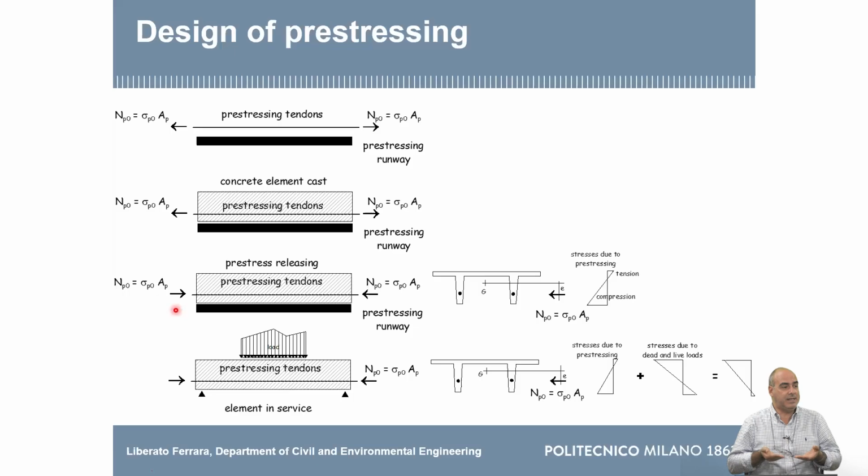It tends to detach from the continuous contact on the bottom and tends to support itself on the edges. But as soon as you do this, the element immediately starts being subjected to its self-weight because you have detached it. So there is never in design a condition where you have only pre-stressing.